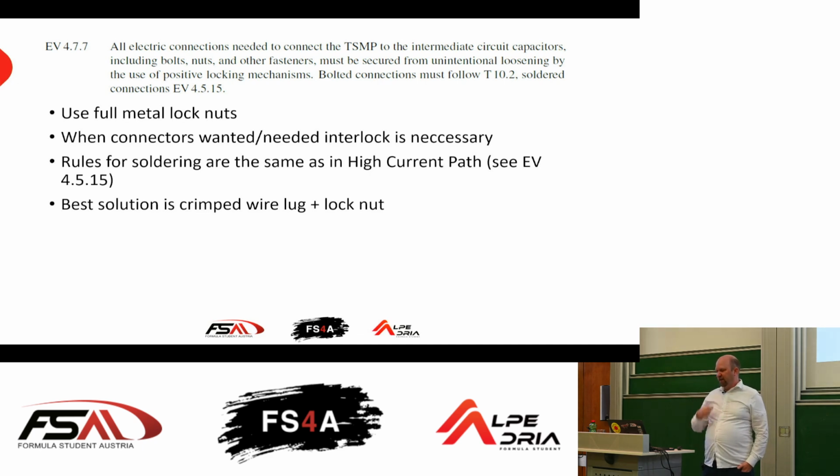When you have connectors, because you have the measurement points, they are in the housing and something like this, the connector must have an interlock. So if you forget to connect it, the car will not start, mostly. And at the measurement points, the best solution is a wire lock and a lock nut.